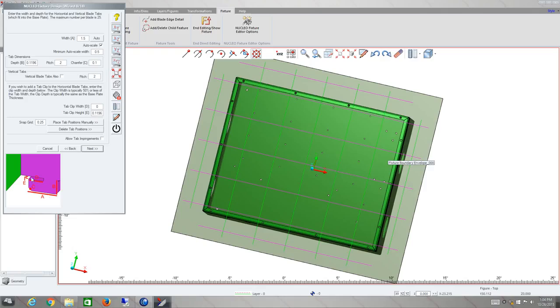If you put a dimension D in there, however, say you put in like a 1/2 inch, it will make an interlocking slot. It'll clip into the base plate and lock the whole fixture to the base plate. So it's a way of creating a breakdown fixture where you can put it together, use it for the welding run you're doing, and at the end you can break the fixture down, lay it down flat, so it makes it a kind of collapsible fixture.